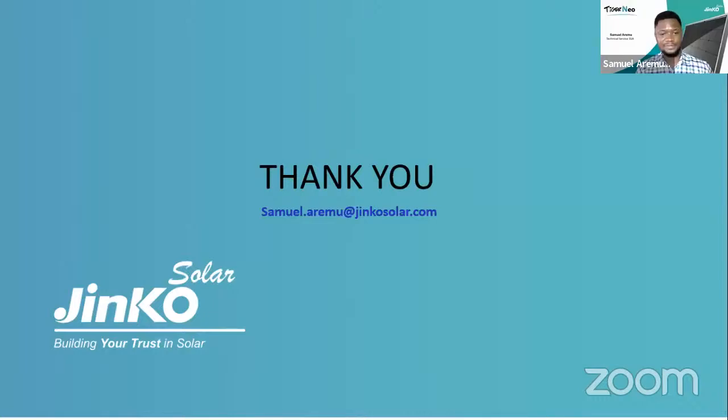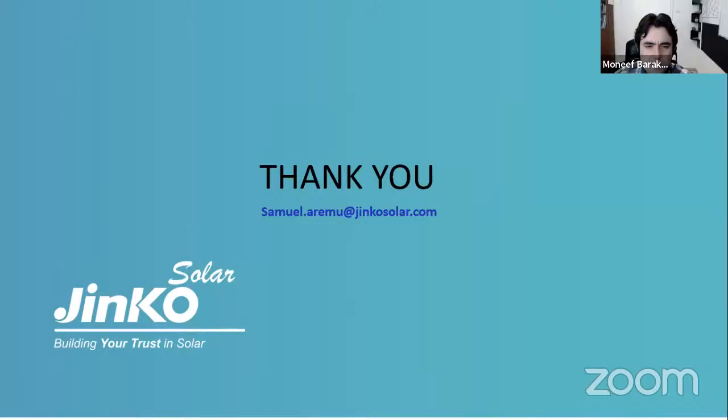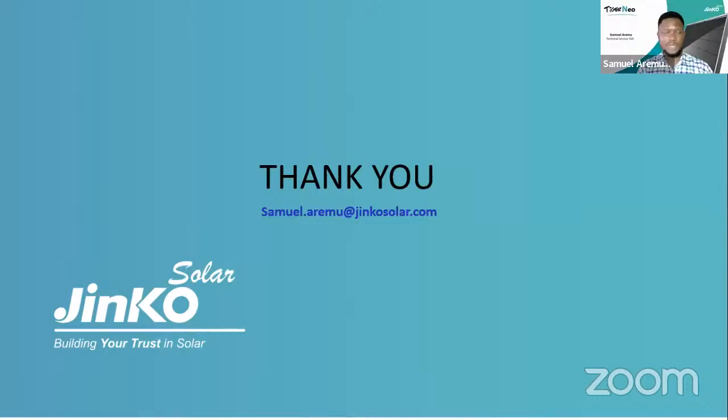That would be better. I have a couple of questions as well, basically the same, asking what's the difference between AC coupling and DC coupling for energy storage. Okay, so for DC coupled, the main reference point is the DC bus bar. That means you are coupling your energy source with the DC bus bar. So in this case, we have the solar PV, and also probably the hybrid inverter or a battery or a solar charge controller, with the DC reference.